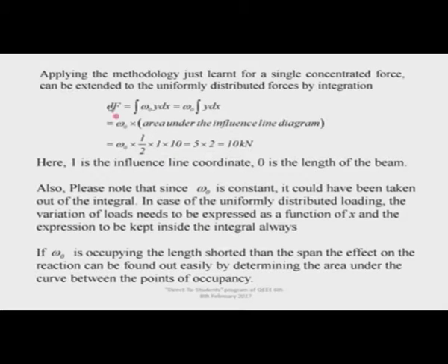When you are finding out for f, the d should not be there in typing. It is a typographical mistake. This integration, the area y dx, is nothing but the area under the influence line diagram, and it gives 10 kilonewton.